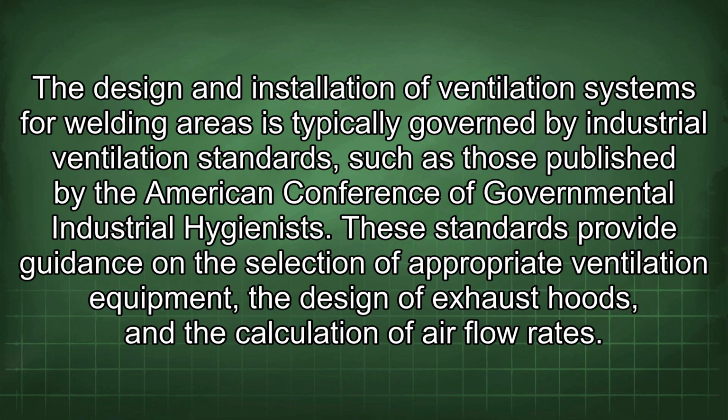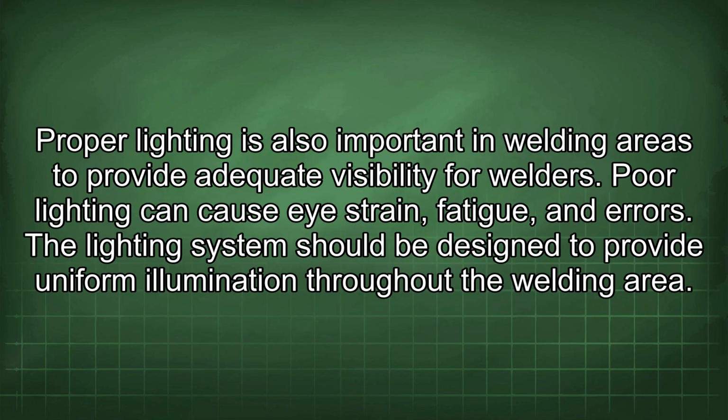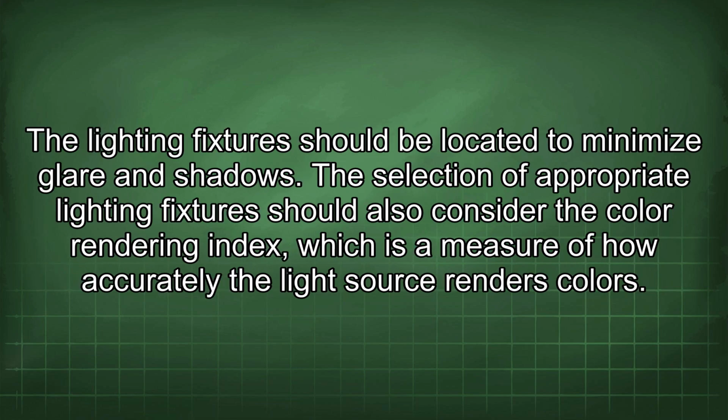Proper lighting is also important in welding areas to provide adequate visibility for welders. Poor lighting can cause eye strain, fatigue, and errors. The lighting system should be designed to provide uniform illumination throughout the welding area. The lighting fixtures should be located to minimize glare and shadows.